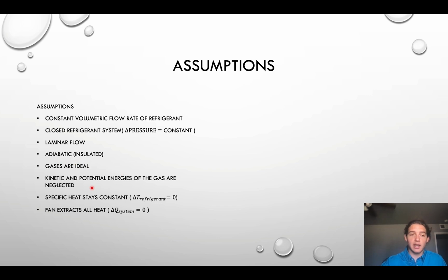The system needs to be adiabatic. The system does not move, so we can assume that kinetic and potential energy are zero. Specific heat needs to stay constant, and there is a fan in the system which needs to extract all of the heat that the system is generating.